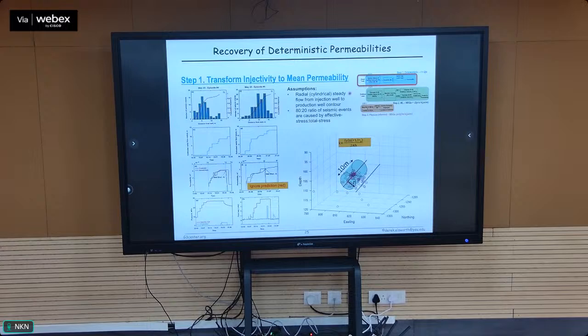So the first step is to be able to evaluate the time history of permeability merely from the injection data. So we have a cumulative incremental number of events, microearthquake events. The cumulative number evolves over the individual episodes, episodes 4 and episodes 5. And so what we have to do is be able to define an injection geometry where the injection along a single well is to an outer pressure boundary, which evolves as the injection experiment proceeds. And we can get the outer conduit of this by merely taking the cumulative number of seismic events that we have, say taking 80% of them, and assuming that this 80% represents the outer boundary of our moving domain, which includes flow. We can use a radial steady solution for flow within that domain.